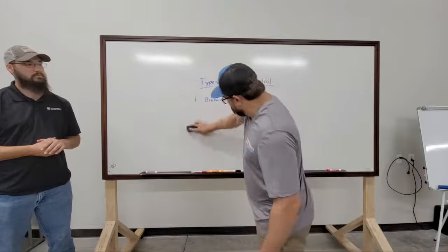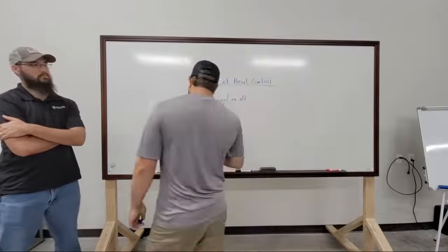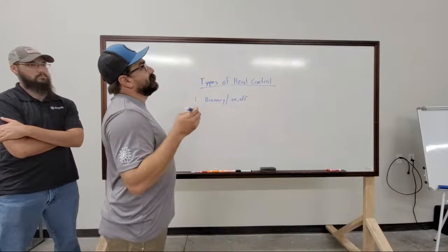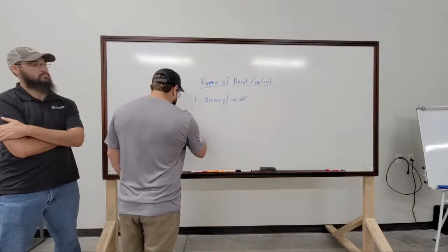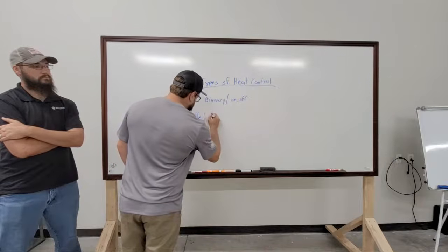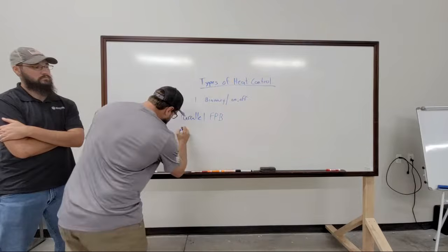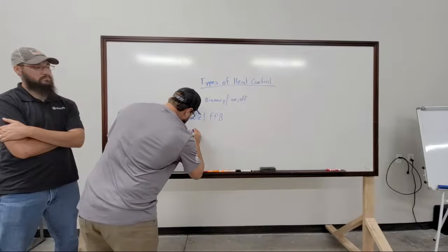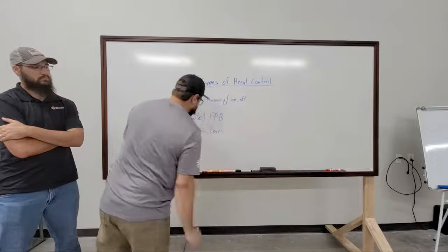so in binary, if you have any fan power box except for a series box, I should say, any parallel fan power box, with staged heating, you will have 1 equals fan for the most part.